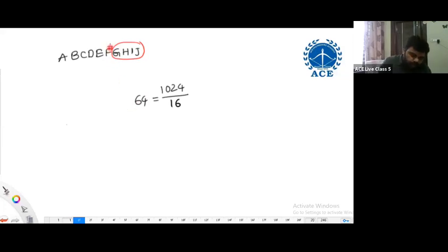So those 4 are using the input variables which are these. That means there is a last stage, and before it, 4 number of 4 to 16 decoders are sufficient to enable the 64 decoders in the end stage.